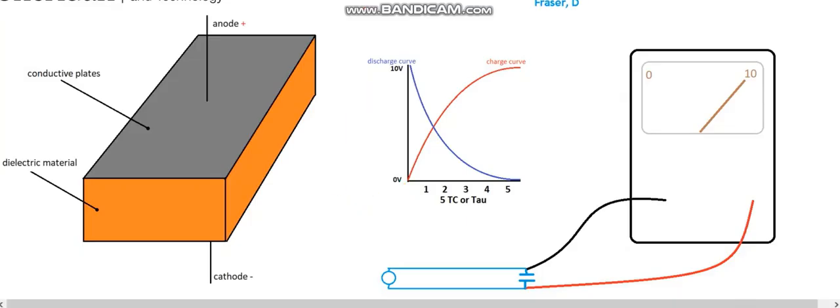And when you see one that's bulging, or looks like it's got something coming out of it, it's bulged, it's split, it's got something coming out, that's a dielectric material. So oftentimes when they go bad over years of use, these constant repetitive firing, discharging, and charging cycles, they will sometimes leak.